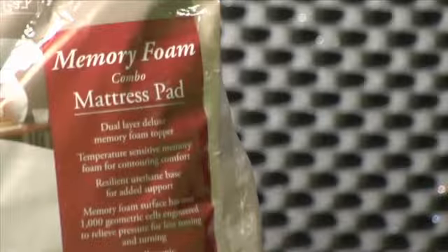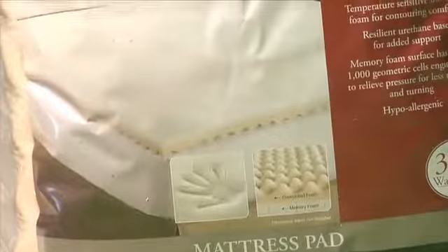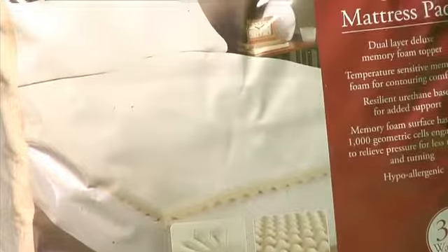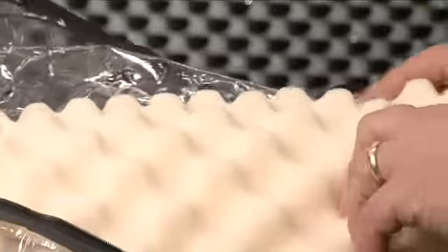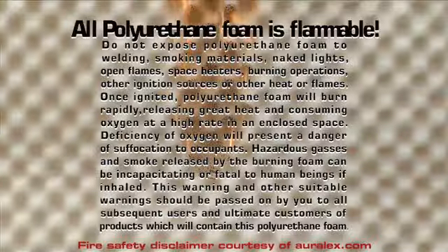While mattress foam looks like the real thing, most bedding or packing foams are not fire retardant and don't perform well as acoustical treatments due to the structure of the foam cells. It's best to steer clear of putting a bunch of this all over your walls, as you will create a fire trap. All polyurethane foam is flammable.